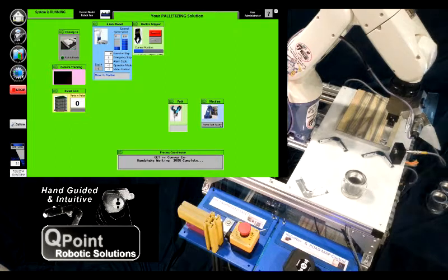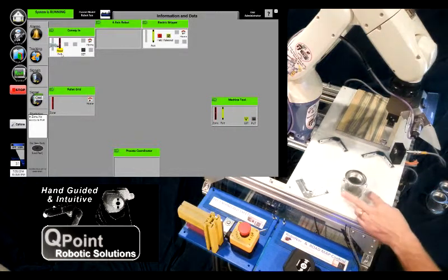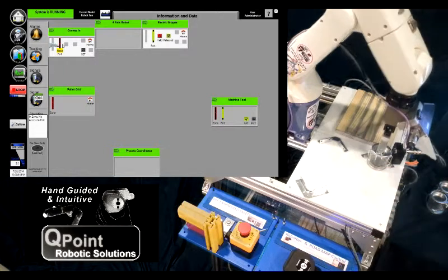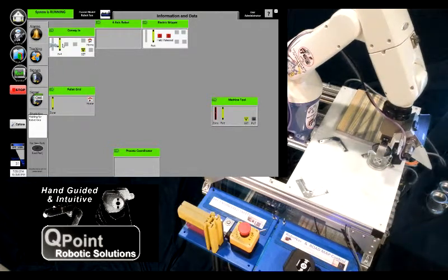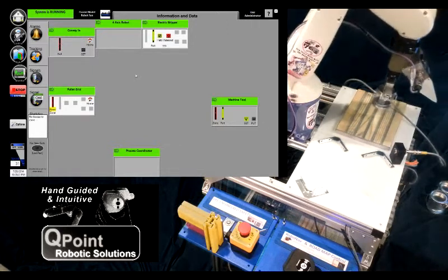And if we go over to the monitor side, you can look at the two apps that are lit up. You have the in-feed conveyor and the gripper. These are the two guys that are working together. And you can see it says, hey, I need access to the part. I don't have access to the part because the signal's not made yet. It hasn't detected the ones there. As soon as that appears, it knows it's there. It can then negotiate, grab the part, and move on to the next process.